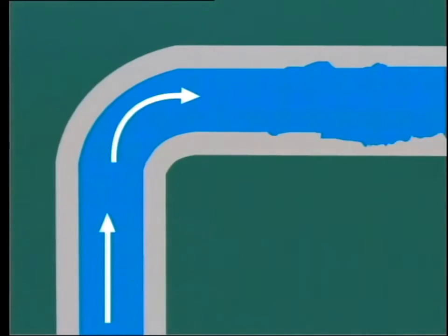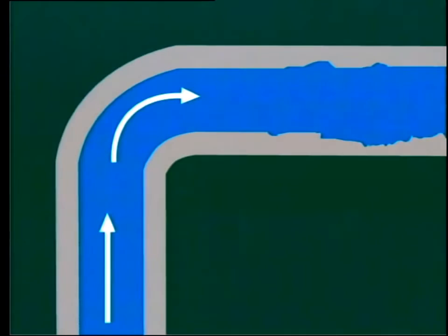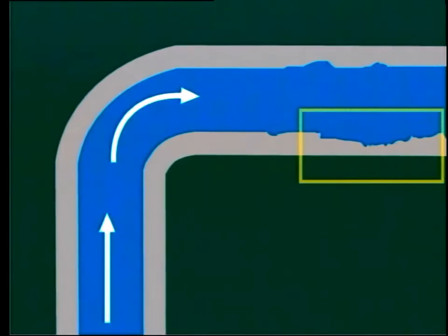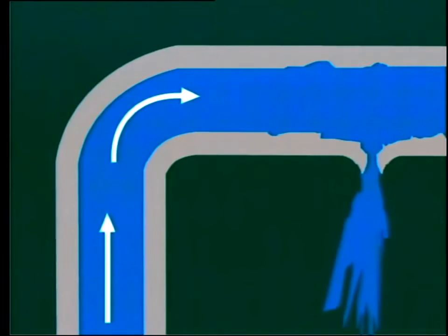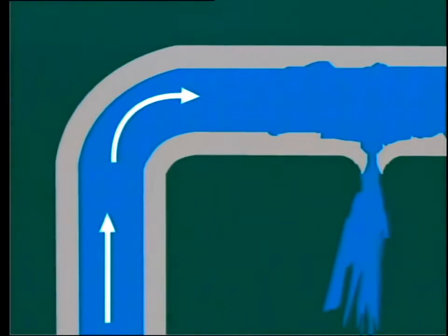Internal corrosion can take place inside boiler tubes under certain boiler water conditions. The corrosive action eats into the tube metal, removing iron and resulting in thinner tube walls. If this action is allowed to continue, certain tubes will fail and will rupture as the thinner section of tube can no longer withstand the internal operating pressure.